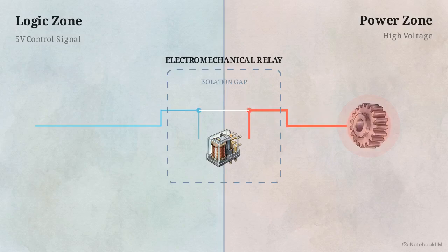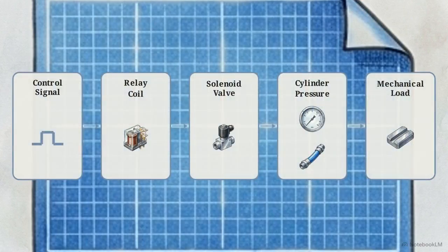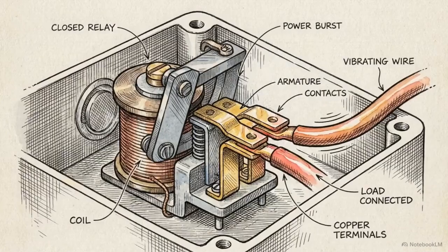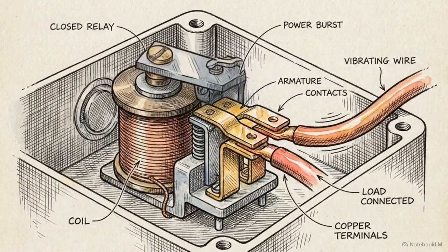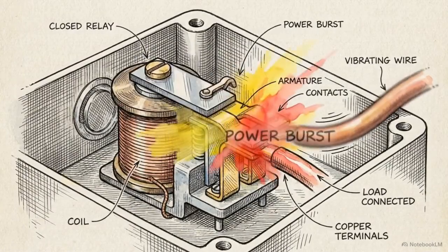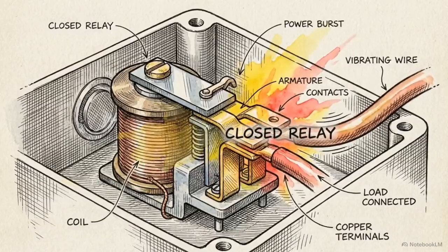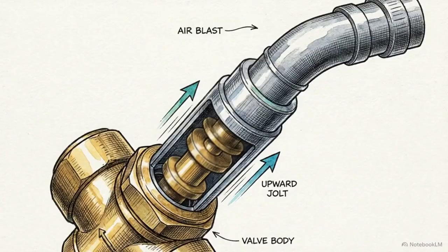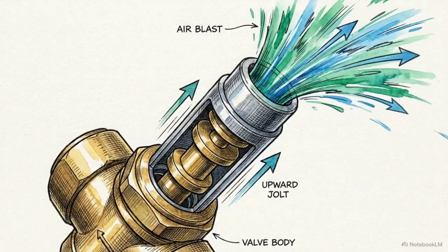Let's trace the entire mechatronic action pathway. It operates as a strict linear sequence of amplification. First, a low-voltage control pulse fires into the relay coil, which closes the heavy-duty circuit to energize the solenoid electromagnet. Next, the solenoid actuates the main valve, unblocking the path for compressed air to hit the calculated surge pressure.